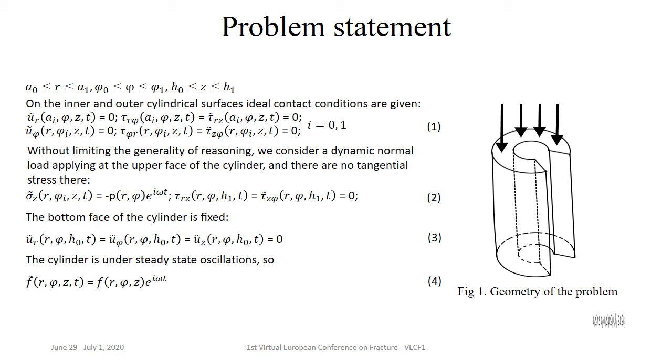It is required to determine the thermal wave field of the cylinder under steady-state oscillations. Such a problem in the static statement was solved earlier. We assume that the temperature field is already known. We note that the problem formulated in this way is equivalent to solving a similar boundary value problem for the dynamic and homogeneous Lamé equations with volume forces of a special form.